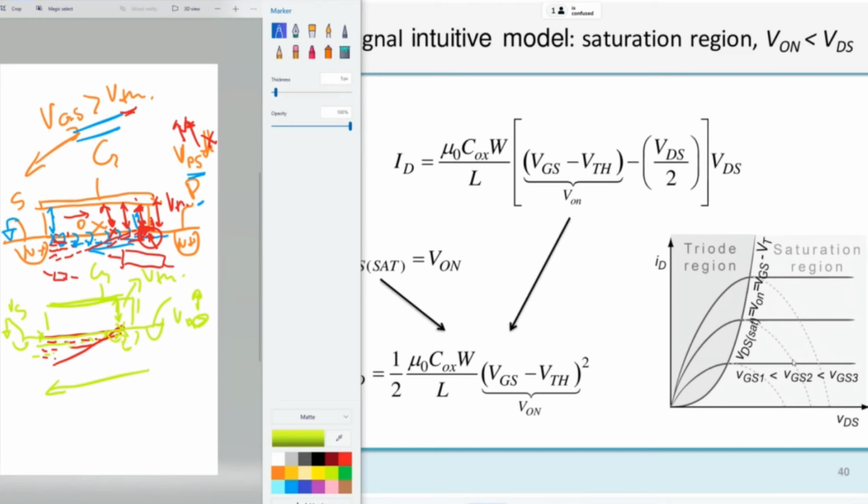And in this depletion region, it will accelerate very fast to the drain and arrive at the drain. So it is a depletion region if you look at it from the vertical electric field. There are no carriers. But if you look at it from the point of view of the horizontal electric field, there will be transient carriers, and these transient carriers will be the electrons which are injected outside the channel, so they are accelerated and get outside the channel.